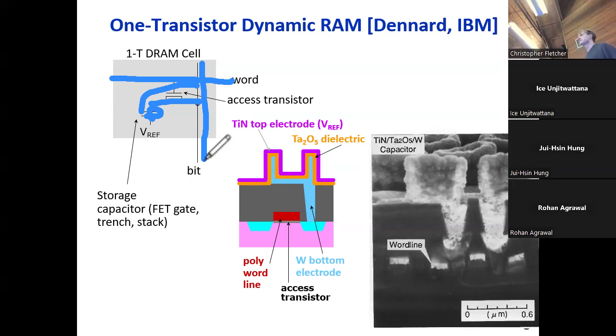Now, because this is a bucket, when we connect it to the bit line, we're dumping the charge out, and therefore the read operation that we're doing on this DRAM cell is destructive. So whenever we connect the capacitor to the bit line, taking the water in the bucket and dumping it out on the bit line, if we want to read the value there sometime later, which we typically like to do in memories, we're going to have to explicitly perform a write back of the original value after the read. The write operation is kind of the reverse.